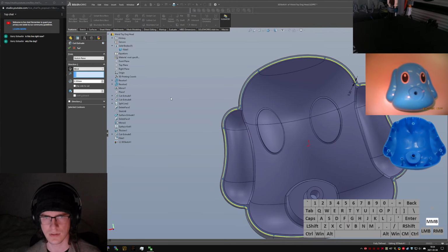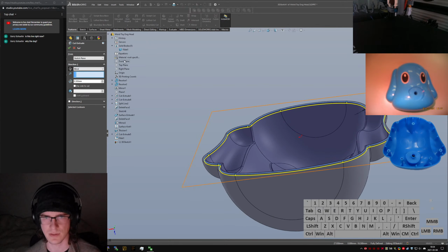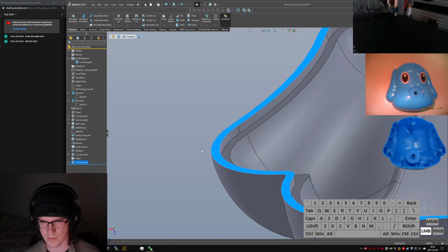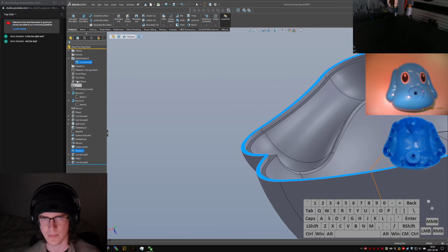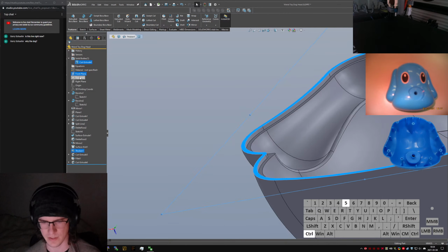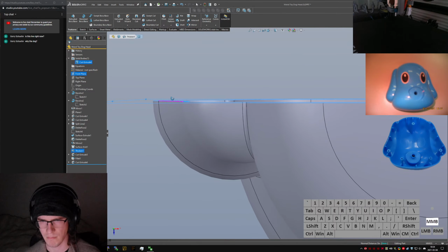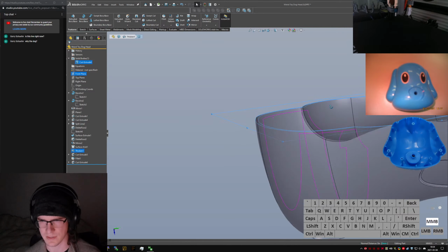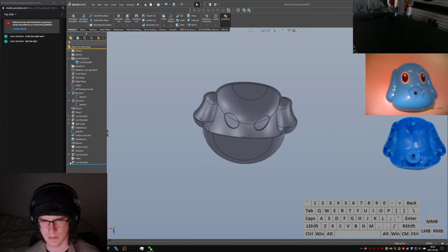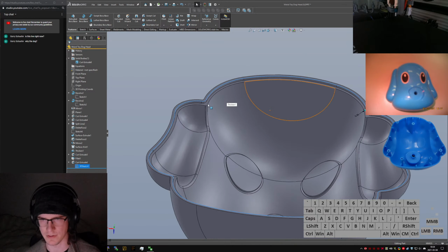Oh, what? Oh, direction of extrusion must be defined. Hang on, I thought this was flat and coplanar, though. This should be coplanar with the front plane. Is it not? Looks like it is. I think it just defines itself as a 3D sketch because it's an offset on face, and those tend to be kind of funky.